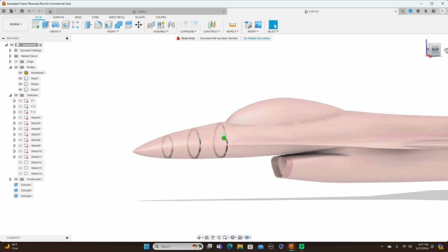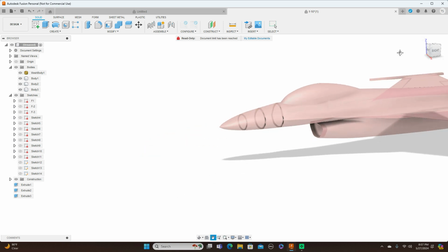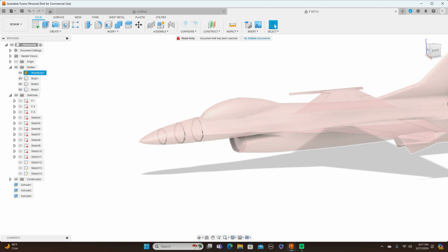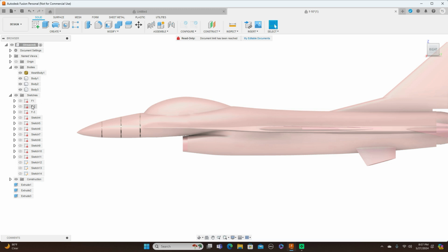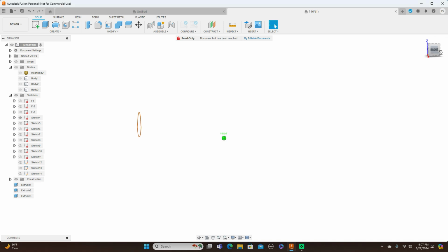All right. And pretty much that's all I'm going to do throughout this whole body back here. And the wings and everything are done the same way like this. So I'll just do maybe one more here to make sure you guys have it down. All right. I'll turn this on. And I'm going to turn these bodies off. Again, come up here to construct, offset plane.